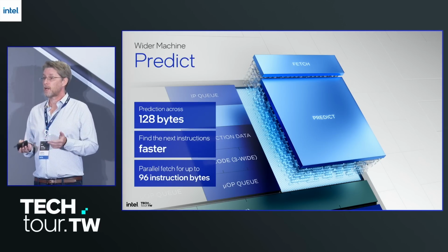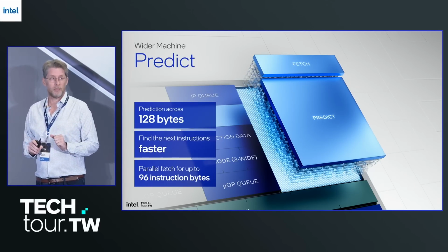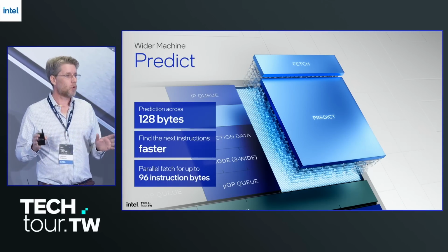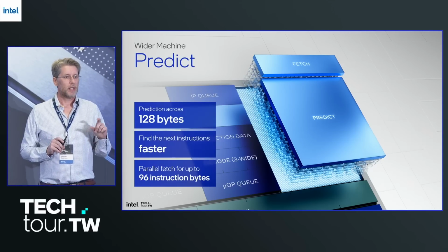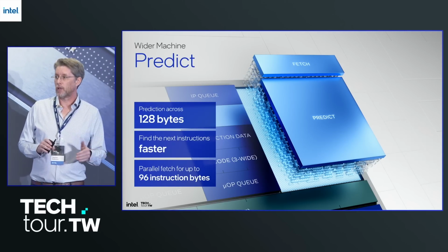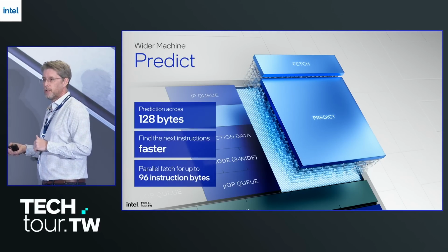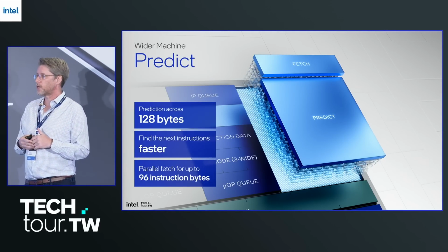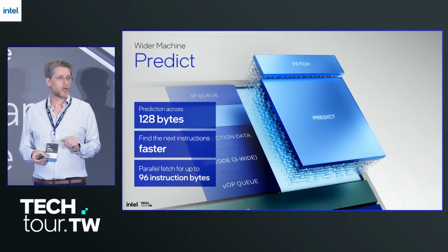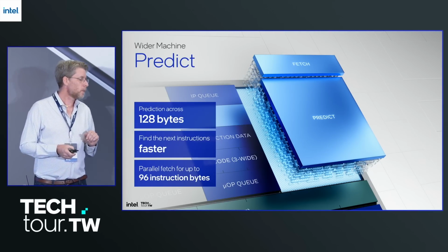In Skymont, we of course made it a little bit larger, but more importantly, we started scanning more data reliably. In the Crestmont E-Core in Meteor Lake, we moved to what we called 128-byte prediction, which means we'd scan across 128 bytes looking for the next taken branch. That's the next instruction in your turn-by-turn instructions.